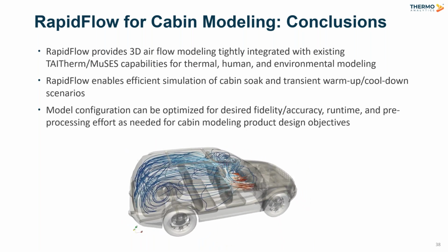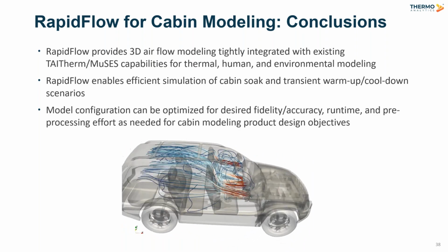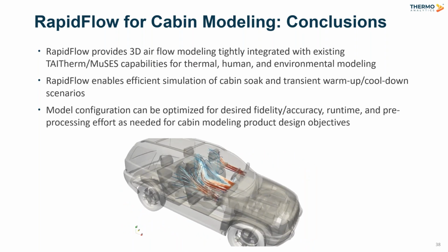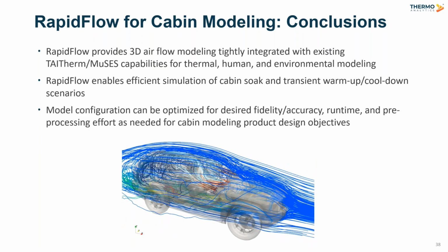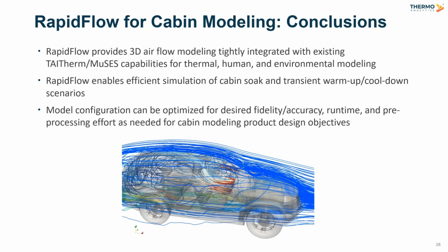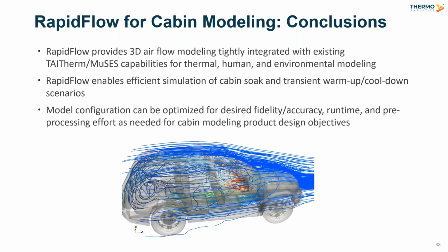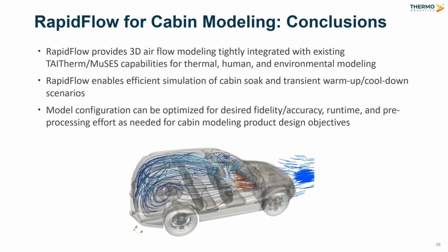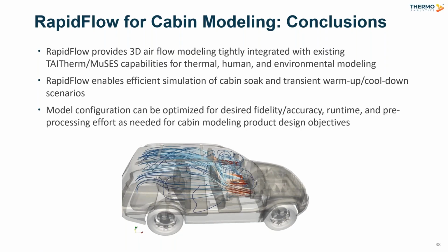Can dynamic boundary conditions be applied, such as during cool down phases with varying mass flow rates or temperature settings? And if yes, can you use thermal comfort to determine the boundary conditions as a closed loop for optimization? Yes. In our cool down example here, we were only changing the inlet temperatures and not changing the flow conditions. But you can change both, and you can change them all with the same methods, either prescribed transient profiles with a curve or dynamic conditions based on input parameters. And yes, you could set up a feedback loop based on thermal comfort to control that.